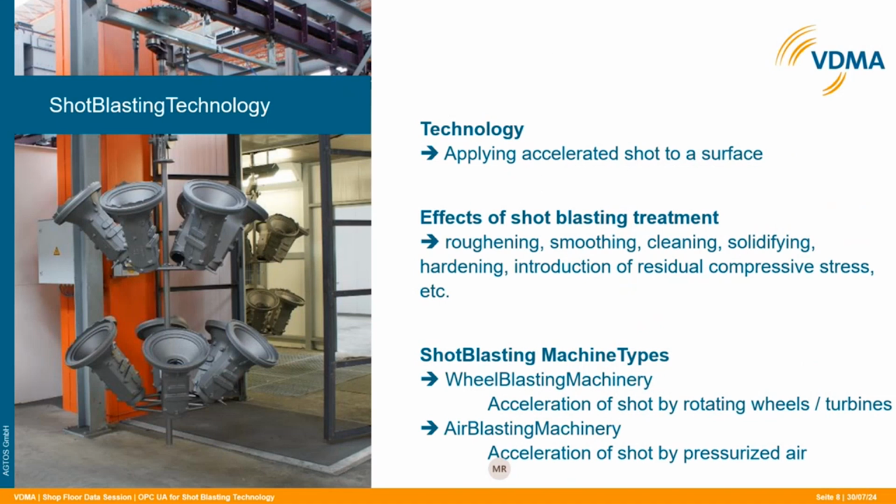What is shot blasting technology? Just a brief view of that. The technology is basically you apply accelerated shot, meaning particles, steel or corundum or nutshells, whatever, to a surface. The choice of shot depends on the result and the substrate you want to treat.